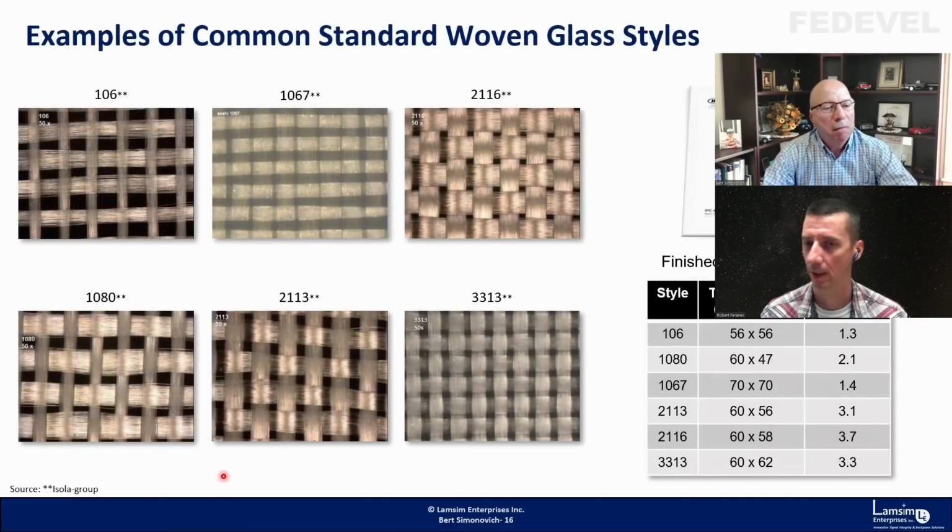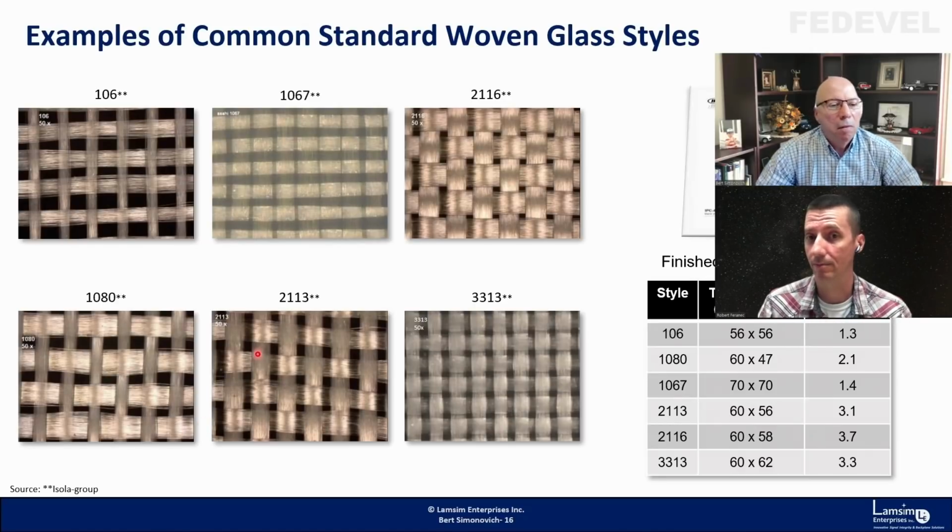So to introduce this topic, for these very high speed signals, everything on your PCB is important. It also includes the quality and properties of the material used to manufacture the PCB. On the PCB there are usually two kinds of materials: one is the copper and the other one is the prepreg. Right. So what is important to consider for these very high speed signals when you are choosing prepreg or core materials?